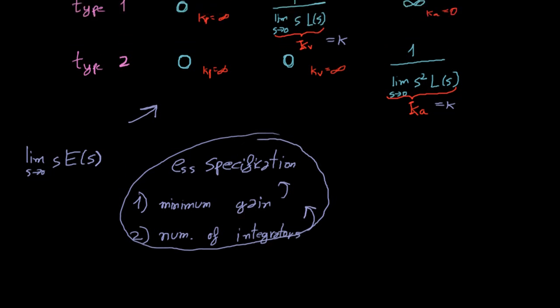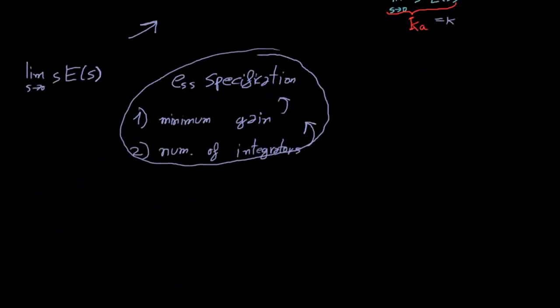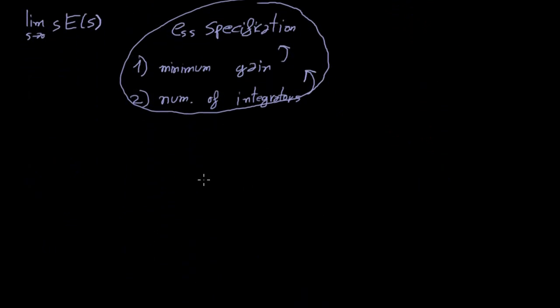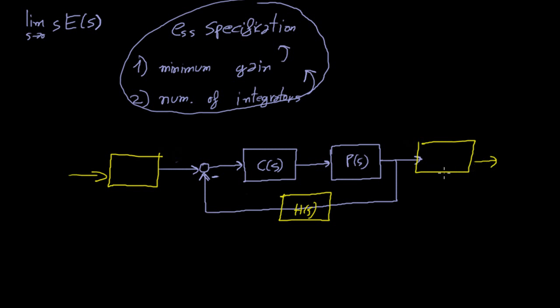Well, another reason why I don't like this table is that it might be okay for simple unity feedback systems. Let me draw one here. Here it is. So the table may be okay for this kind of system, but for systems with non-unity feedback, or in series with other systems, or even part of more complex systems, the table may be deceptive.